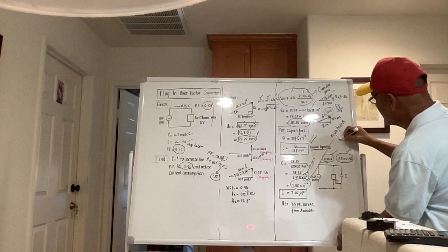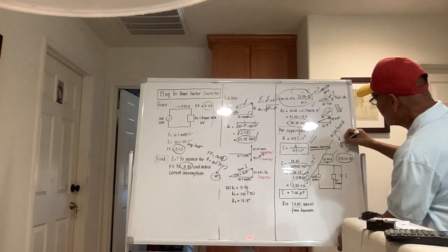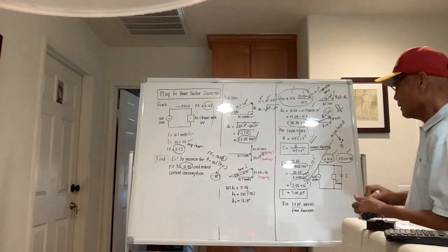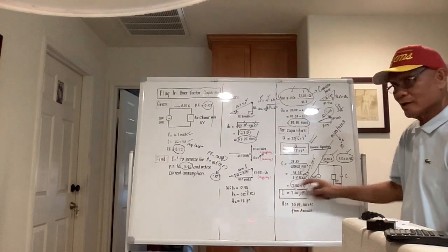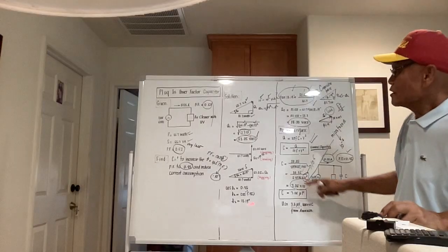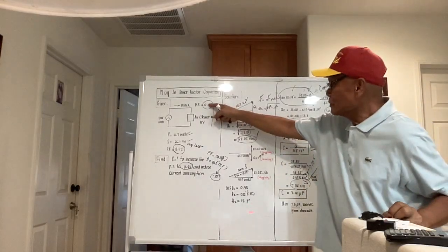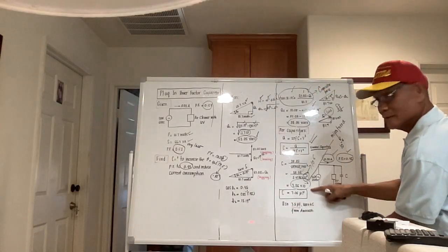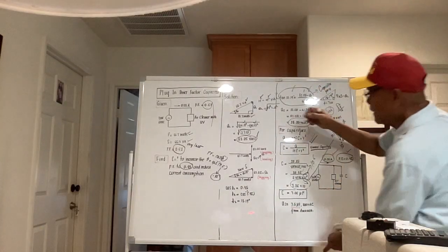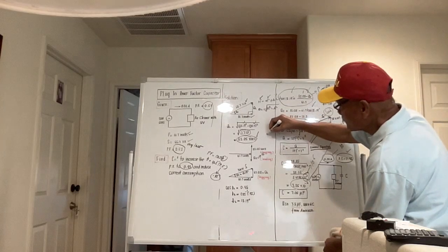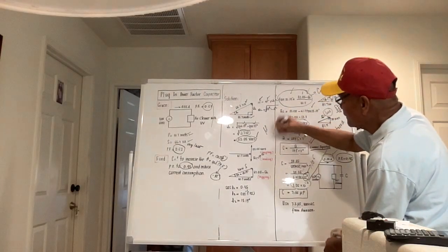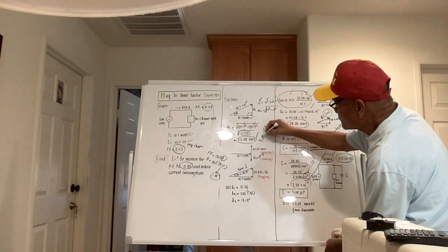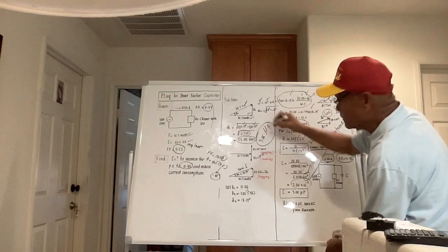If we see micro, the multiplier will be 10 to the negative 6. So according to our computation, the required capacitance of the capacitor to increase the power factor from 0.62 to 0.95 will be 7.06 microfarad. The symbol for micro in AC circuits is this one here. That's micro. Capital letter F is farad. We need a 7.06 microfarad capacitor.